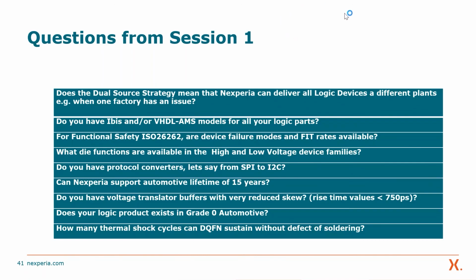No, I'm not directly aware of what we can do now for 150 degrees, but I can imagine that with the new packages it would be rather possible, because newer packages are all implemented in copper, and the very much limiting effect of former packages was the gold contacts. And I think that with the future move towards more copper technology, moving to 150 degrees should also be more easily possible. Okay, so to the guests that asked that, please contact your local sales or application engineer.